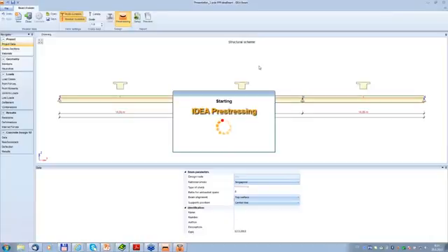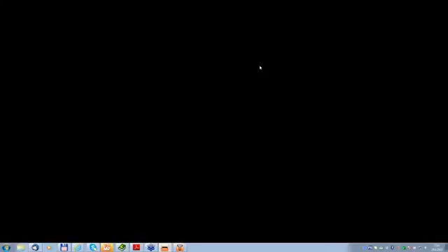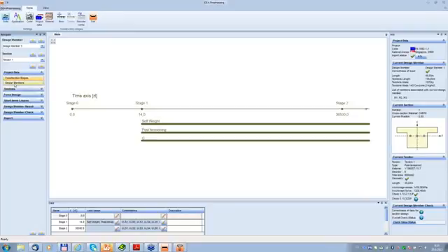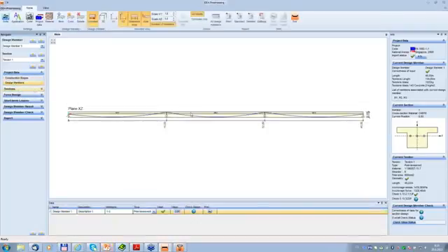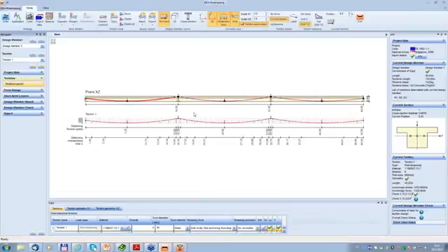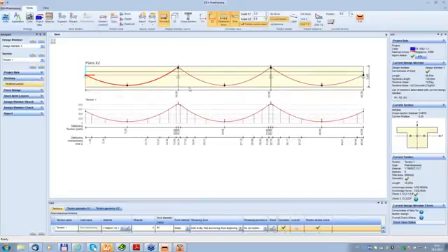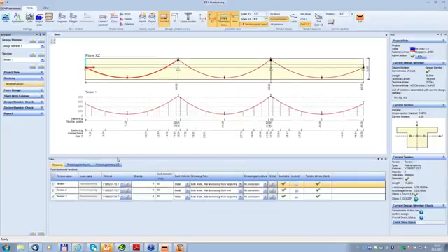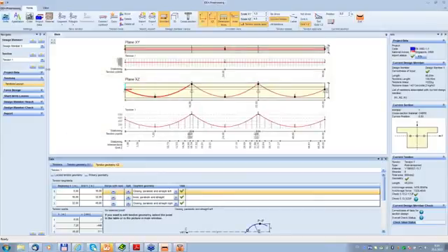Now I start the module for IDEA pre-stressing, and I pre-stressed it. Those are a kind of construction stages, design members and tendons. I can make this scale more appropriate so that we have now scaled the picture in the XZ plane. You see the tendons. You can edit the tendons, change the geometry XZ. XY is here. You can see the force design, so equivalent loads.